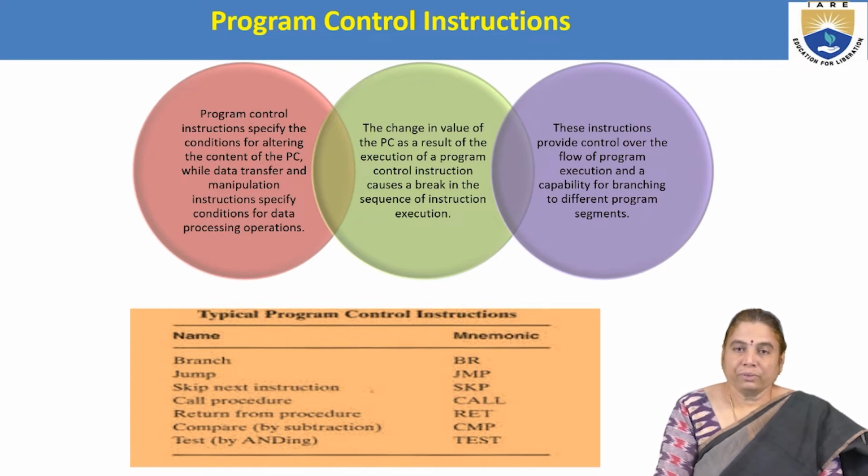The list of instructions available under this category are branch, BR, jump, JMP, skip next instruction, SKP, call procedure, CALL, return from the procedure, RET, compare, CMP, test, TEST.